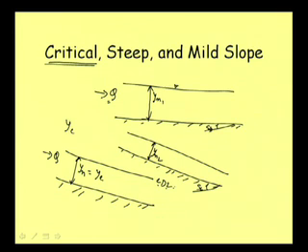But here just know that we can have a slope where we can have uniform flow at the critical depth. That means, with minimum energy, for this discharge the water is flowing with minimum energy, and that particular slope is called the critical slope. We will write this as S C, the critical slope.